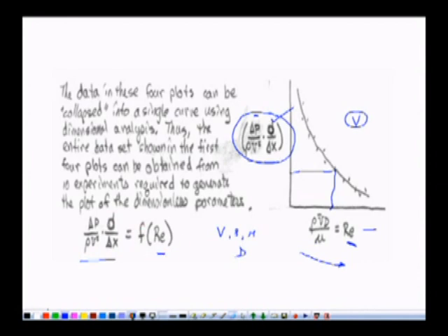So, we have merged these independent variables into these 2 dimensionless numbers, and simply by changing the velocity v, we are changing the Reynolds number, we are changing this number also, and we can conduct the experiment simply by changing the velocity, and now we can answer questions with the help of this one simple experiment, right.